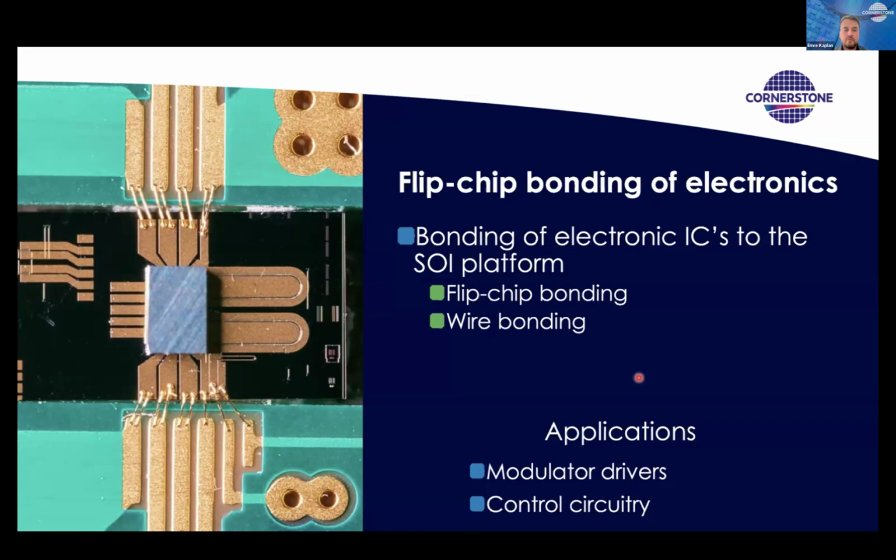So we have a new tool in the clean room right now. The colleagues are working on optimization and creating this process. It is mostly for bonding an electronic chip onto the photonic chip and then the wire bonding to the PCB. By doing that, you can have modulator drivers on the photonic chip.